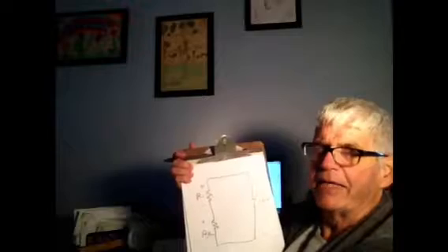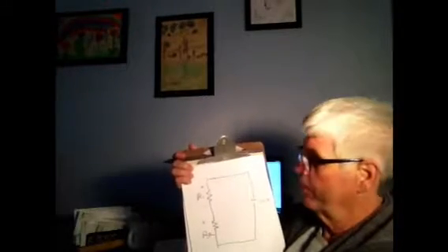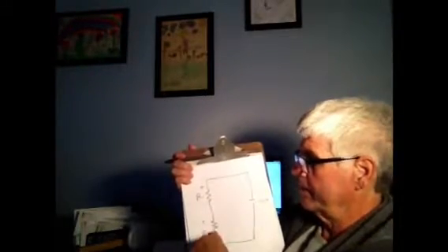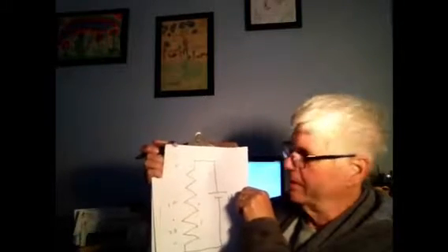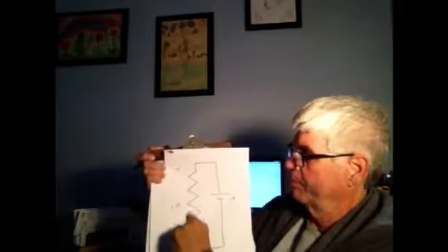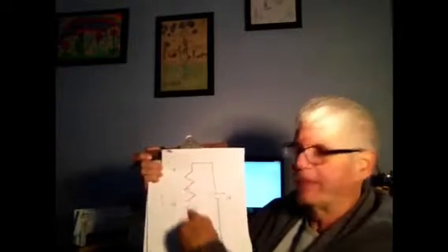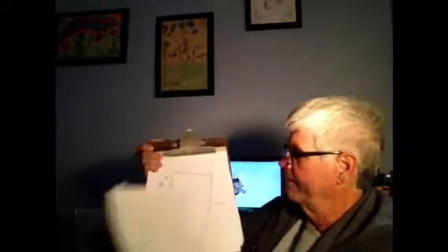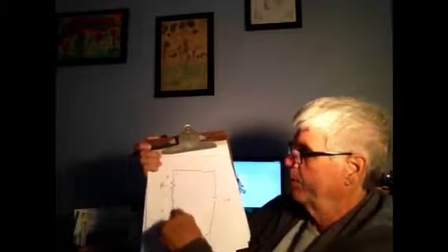Well, it turns out it divides in proportion, or in ratio, to the total resistance. Just like our other one over here, we had a total resistance, and the voltage divided by the proportion of how far up and down this resistor we were. The voltage here is going to divide per the proportion to the ratio of the resistance.